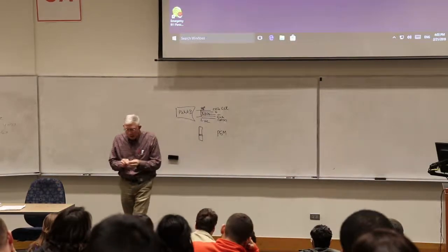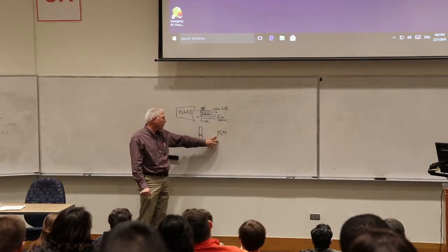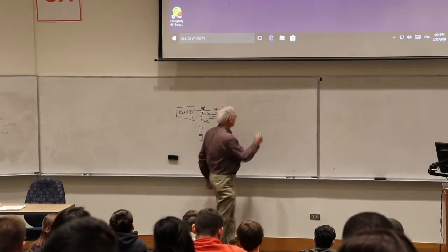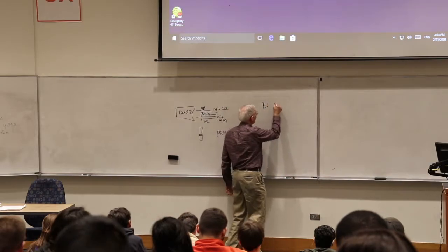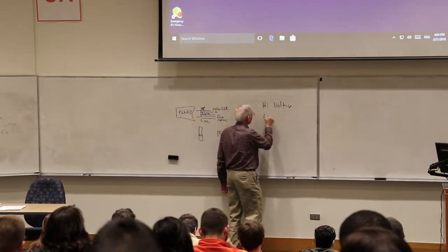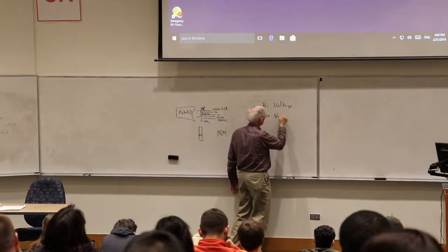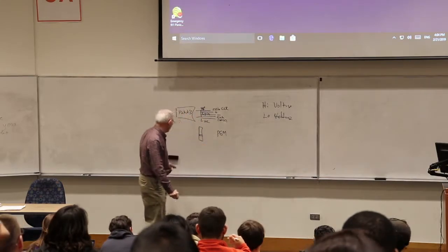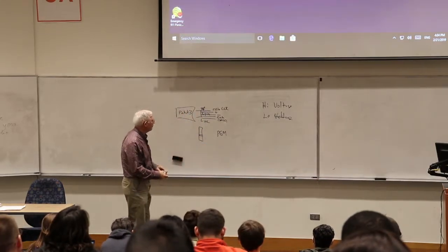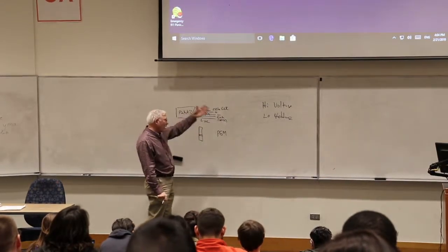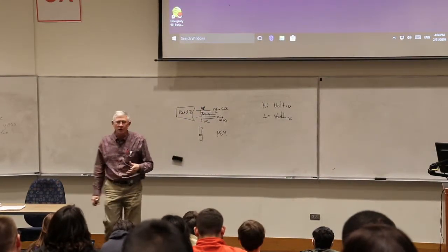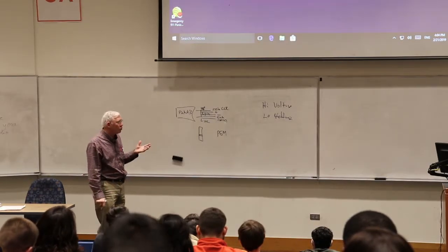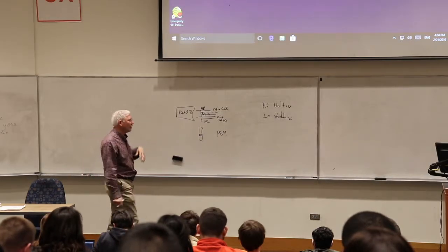Now, back in the day when we had this program pin, there were two different ways to program the device: high voltage and low voltage. It's embarrassing when an electrical engineer can't spell voltage, but that's how it is. In the old days, the high voltage was actually like 14 volts. It was pretty high. Nowadays, I think it's 3 volts over VCC or something. I don't know. It's not that high.